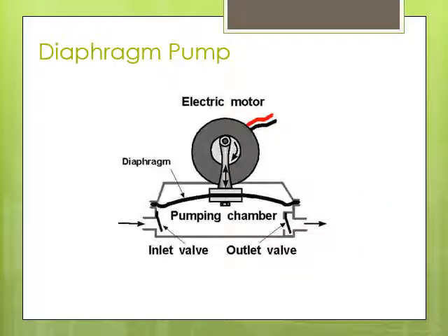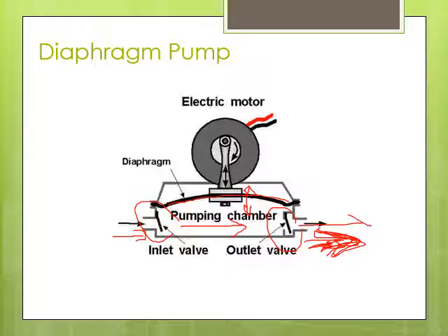Essentially, they have a flexible rubber membrane that moves up and down with this offset wheel. And then they have two check valves where the water comes in and goes out. I'm really not good at drawing, I'm left-handed, but I write with the mouse with my right hand, so it makes drawing really hard. Anyways, these flapper valves trap the water so it can only go in this direction. So every time that rubber diaphragm pushes down, it squirts the water out, and then when it sucks back up again, it pulls the water in. But because it's a rubber membrane and a plastic housing, it's corrosion resistant.